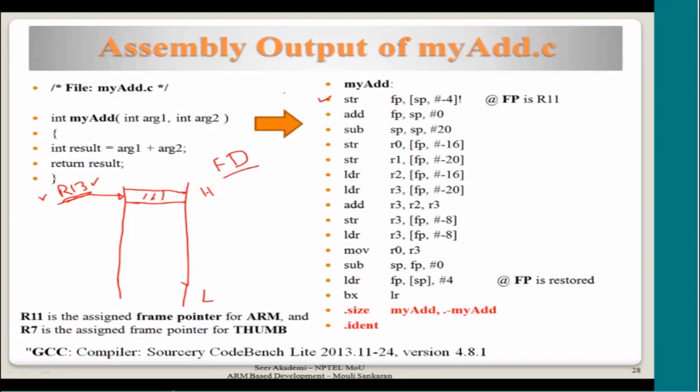So this is the first instruction. As soon as the BL myAdd was done, let me link you from that assembly file to this. When this was executed, there was some instruction after this. Let us call it some XXYZ. Some instruction is there residing at this address. Now, after this particular BX branch is done, with respect to LR, the link register, it is supposed to go back to the address next to this BL instruction before this function was called.